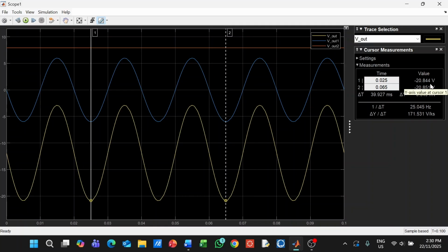So in the physical implementation, the op-amp cannot produce output exceeding its power supply range. In fact, it can only produce a value slightly greater than negative 5 volt, maybe some value around here. So to preserve the original simulation output in the physical build, we should increase the magnitude of the voltage supply. Maybe we can use positive and negative 25 volt as the power supply.